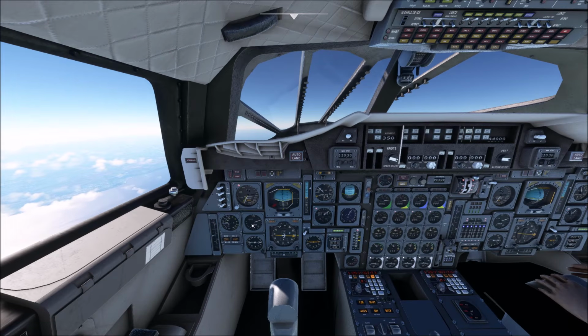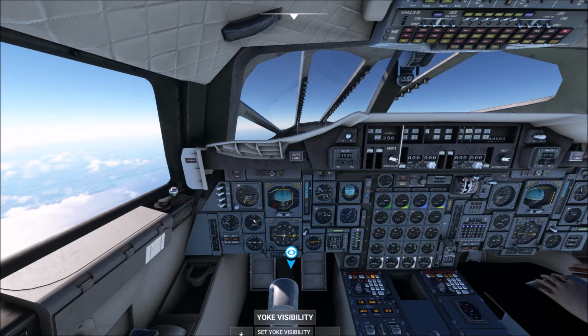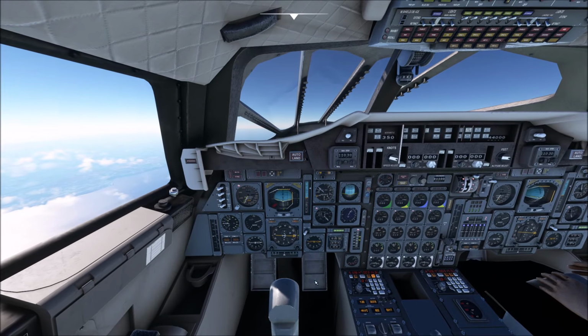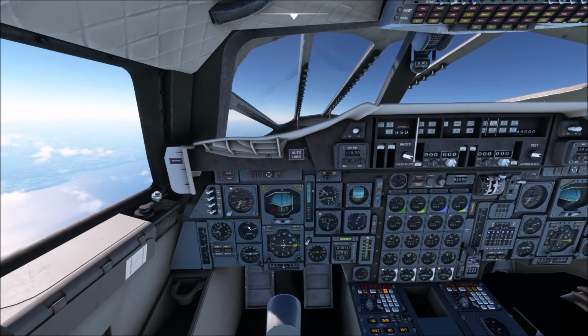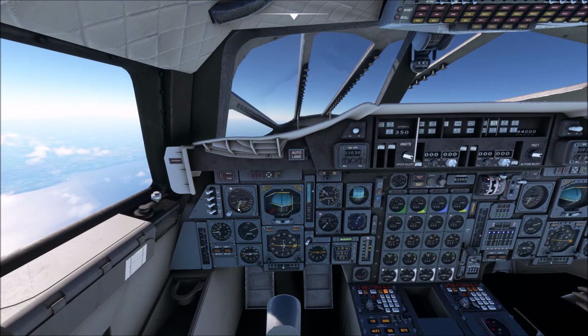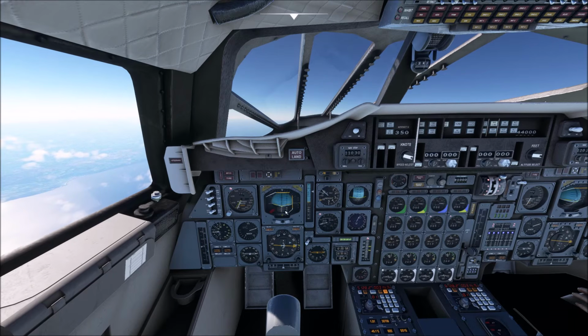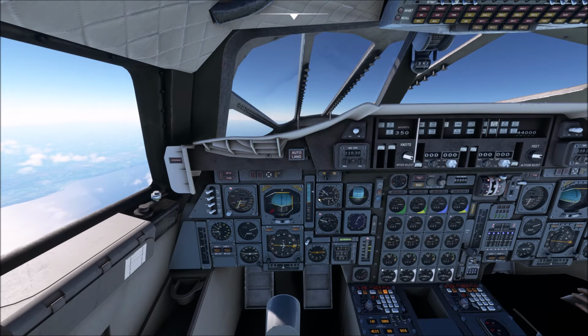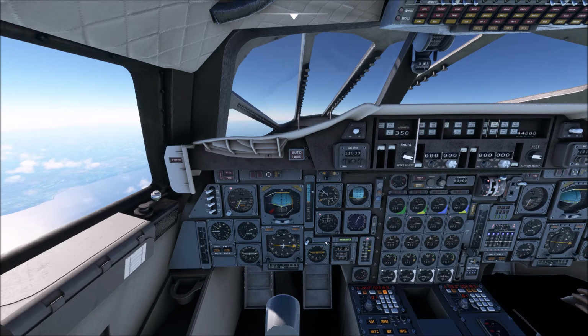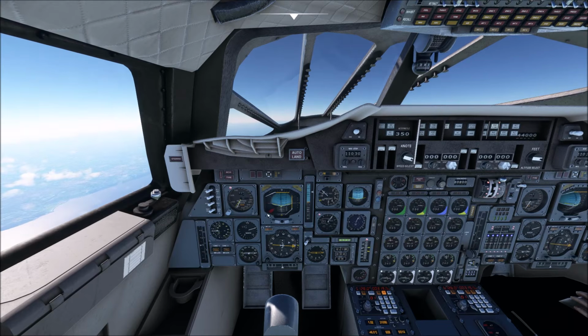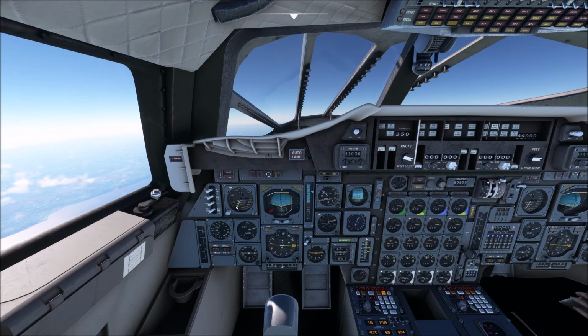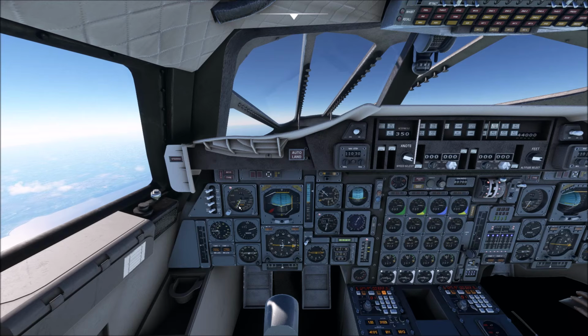We'll keep accelerating, just hitting Mach 1, there we go, just hit supersonic. And what will happen now is we're almost reaching the speed limiter, the barber pole there. We're over the Bristol Channel now. And Concorde will then use attitude to control airspeed. So in full burner it will climb as quickly as it can. As we get higher, the maximum enabled Mach number and indicated airspeed will increase. And thus Concorde will read that and keep pushing us up to speed.